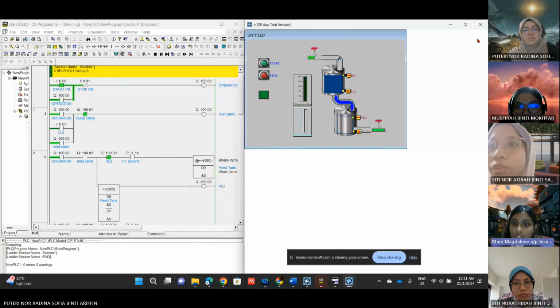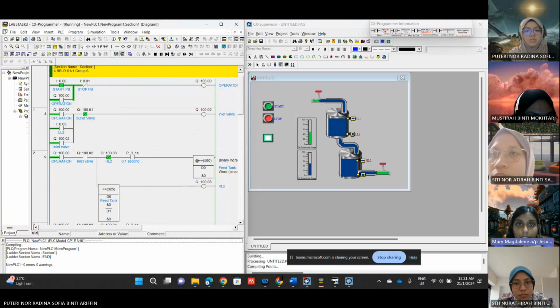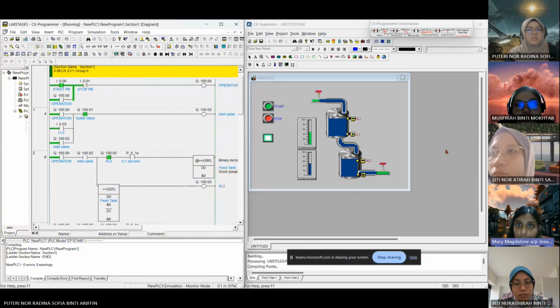As for discussion, in designing the PLC SCADA program simulation for the liquid level control system, careful consideration in variable definition is paramount. Employ analog variables for precise representation of liquid levels in storage and feeder tanks, and use digital variables for tracking the status of level switches and valves.